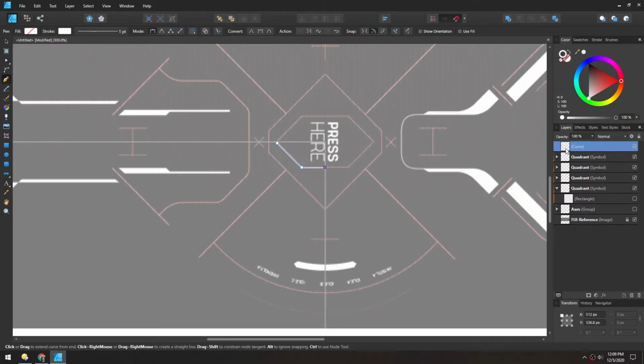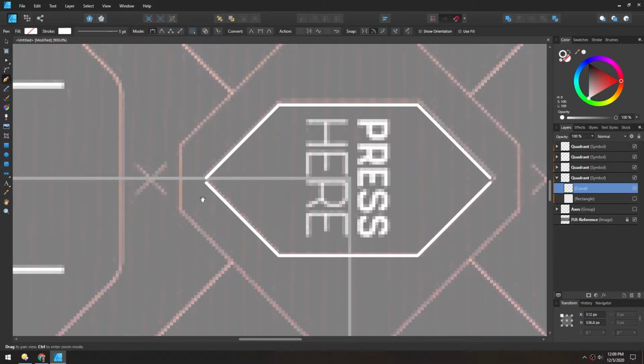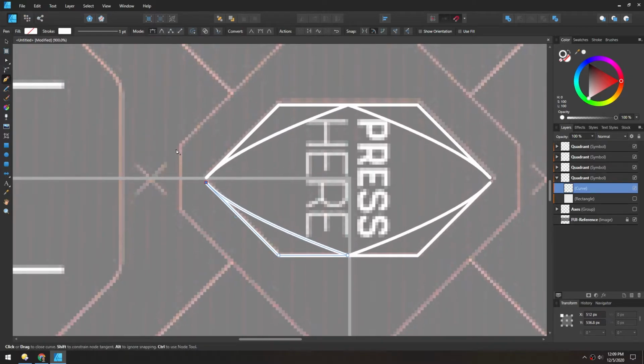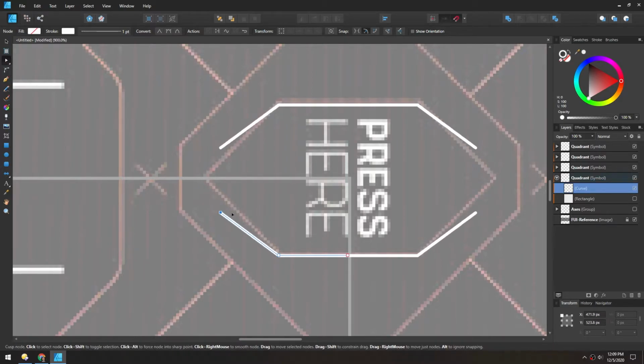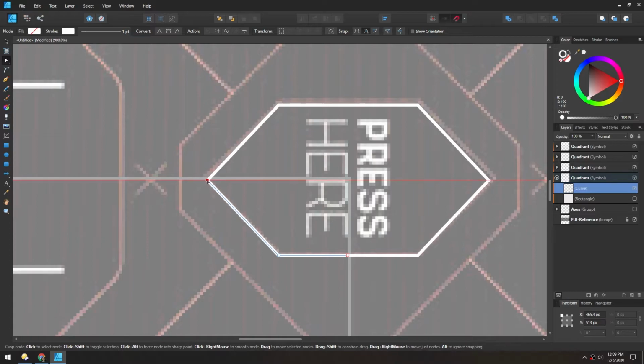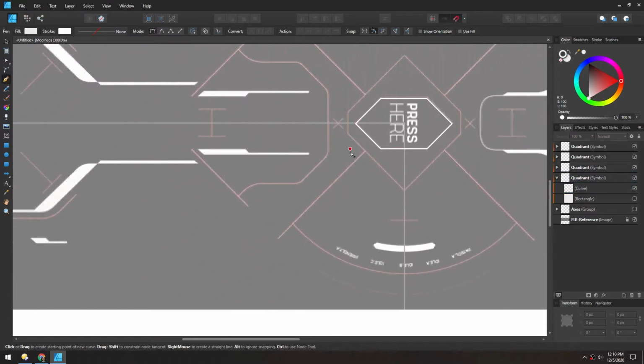And as you can see, this curve is outside of these symbols, so let's just drag it inside. And now you can see the shape goes all the way around. And any place where we hit an axis, we'll have to make sure it goes all the way up. So I'll select the node tool up here, or you can hit A. And then I can adjust this and make sure it snaps right on there. Back to the pen tool, and I'll just start tracing all these lines.